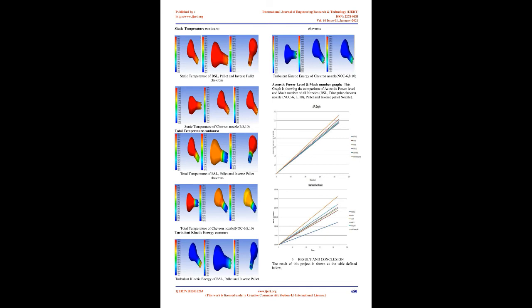For example, in designing a chevron nozzle, we consider the exhaust diameter of the nozzle as 50.8 mm, tip angle, ss, as 60 degrees, penetration angle, a, as 5 degrees, and number of chevrons, n, as 8, so the configuration will be N8SS60. For that nozzle, the base of the nozzle, from Eq. 1, equals.